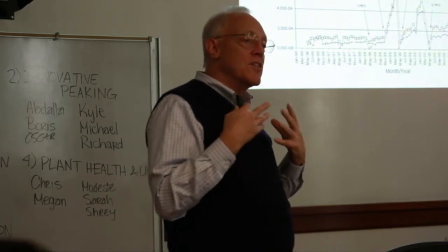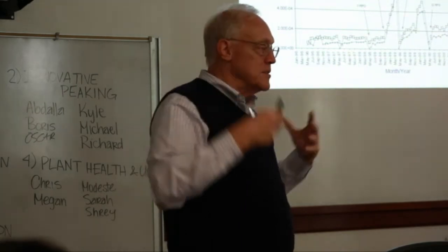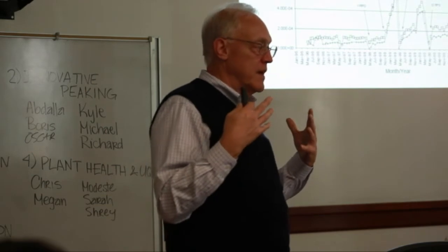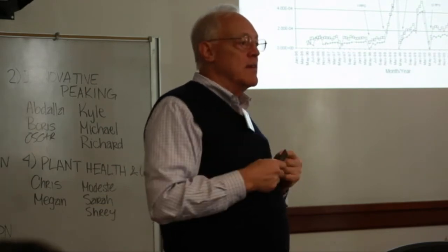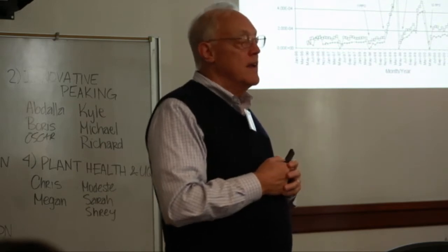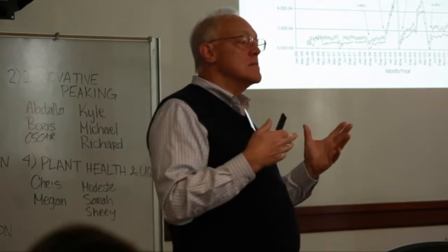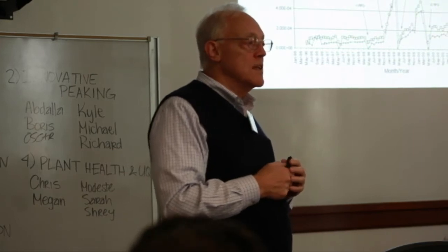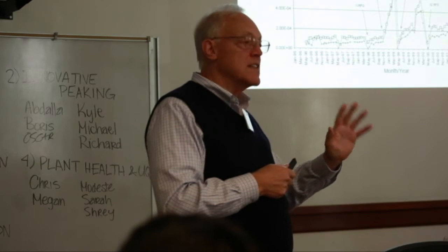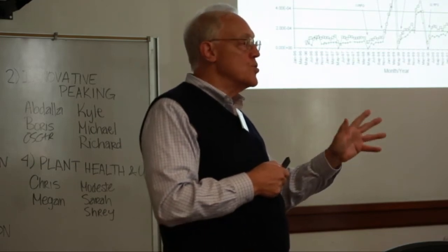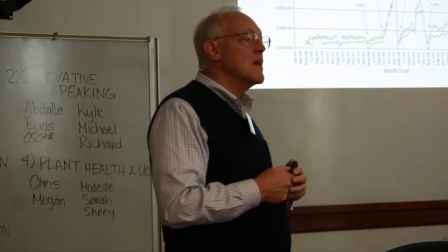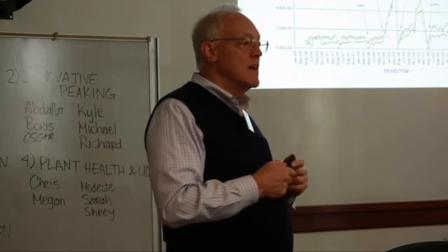Now the device I do that with is this big hunk of instrumentation that's twice the size of that podium. I suck air out of the containment and I have filters on it in addition to the monitoring stuff. And normally, operationally, I replace those filters every month. Not because I need to, because I do. Because I want to make sure that they're not clogging up in the interim period for some reason. They were replacing those filters every other day.